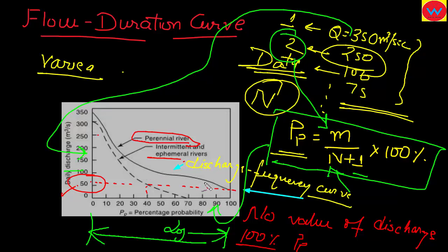It is due to the smoothing of small peaks in monthly data. The presence of a reservoir in a stream considerably modifies the basin flow, as we have seen earlier. It basically changes the peak value of runoff, and it hides the actual natural flow of that catchment basin.